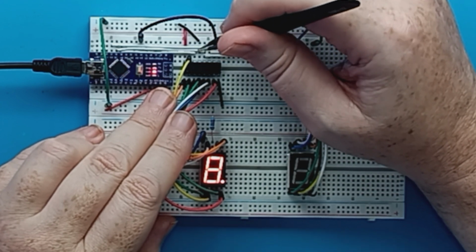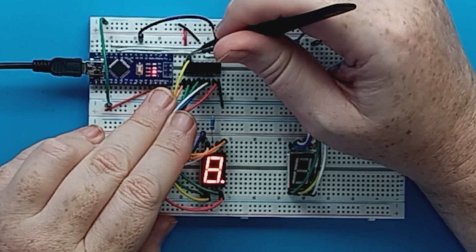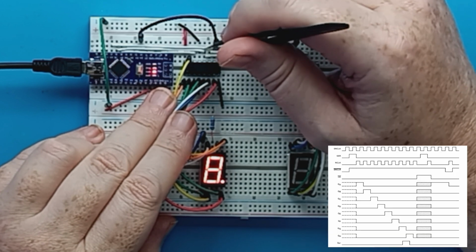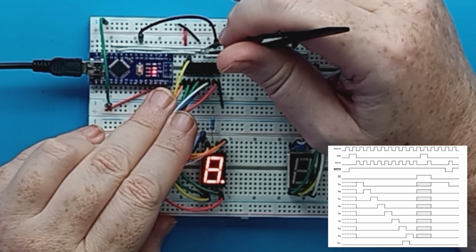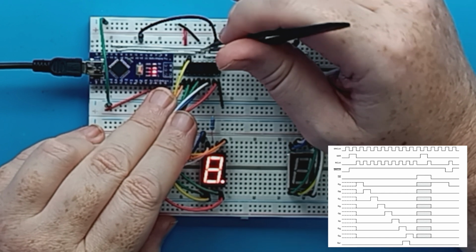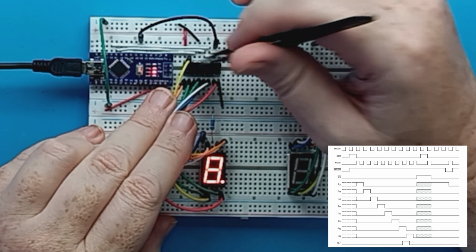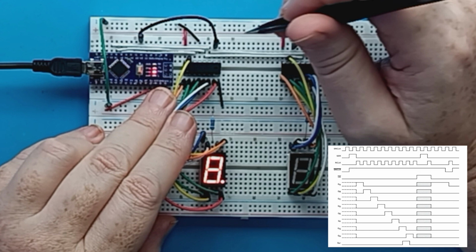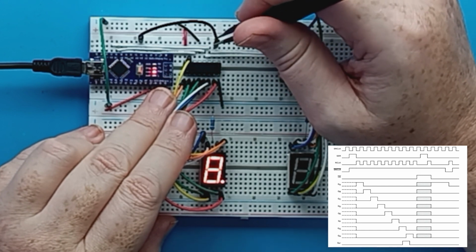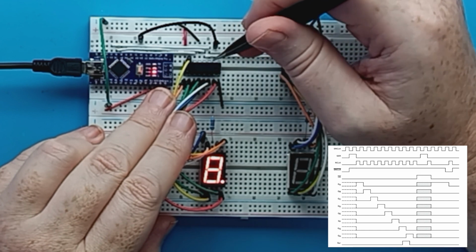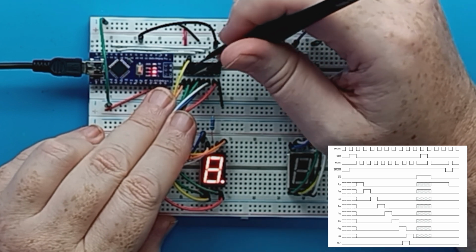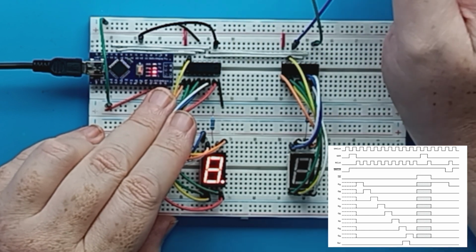So in order for this to work, we put the serial data in, we use the serial clock to bring it into the register, and then we invoke the R clock to latch it to the output. There also is a clear line which resets the registers inside the chip.